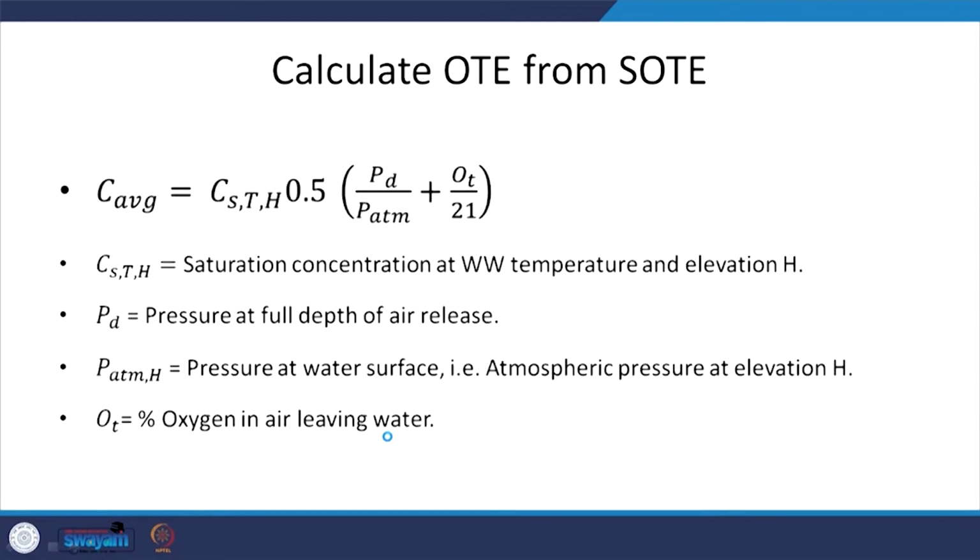Again, all these formulas will be given, so you don't need to worry about it. So how will I calculate the CS average? We have the saturation concentration at the wastewater temperature and elevation H, the elevation of that particular location, and pressure at full depth.